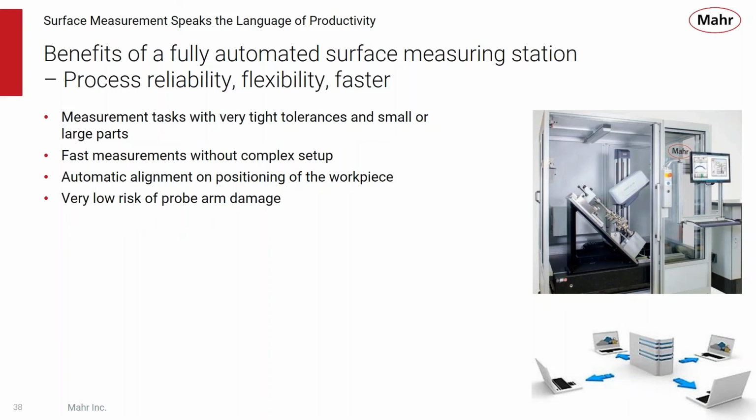So the benefits of an automated surface measuring station: reliability, flexibility, and speed. Measurement tasks with very tight tolerances or small or large parts can be done very quickly. Fast measurements without any complex setup, because the setups are programmed in there and pulled up by part number. There's automatic alignment and positioning of the workpieces. And because they're all automated and driven, there's no risk of probe, drive, or arm damage.